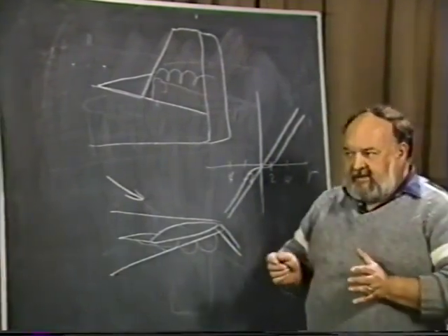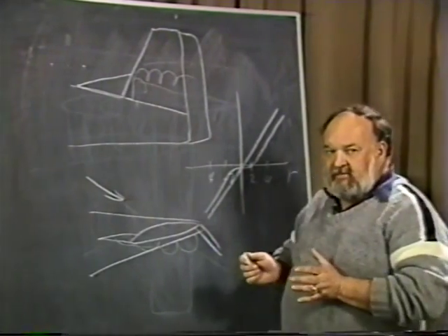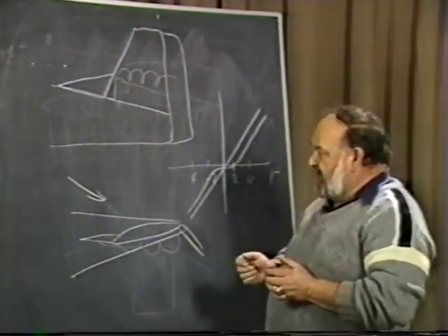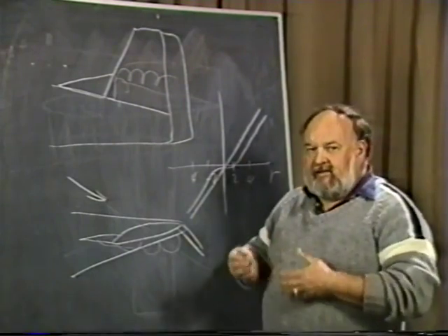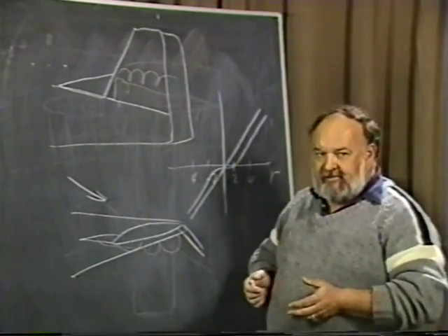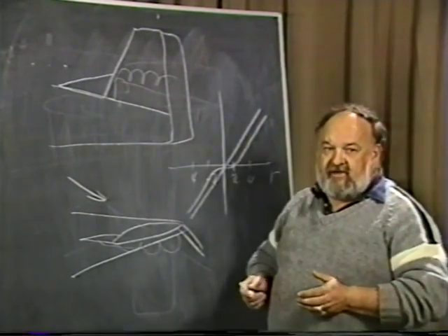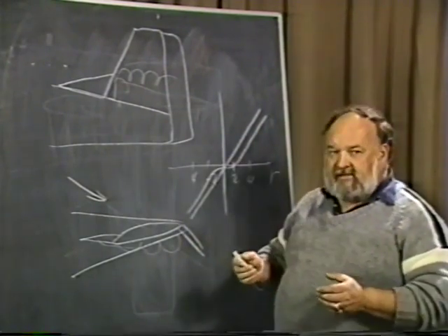When you have an airplane that sits there and it's loose in directional stability, that's the way the pilot would feel, and then it starts to get heavy as you start to apply controls into it. You get these unbalanced, uneven forces. A dorsal fin is a very strong and powerful thing to fix that. On a Yankee, that's exactly what we did.